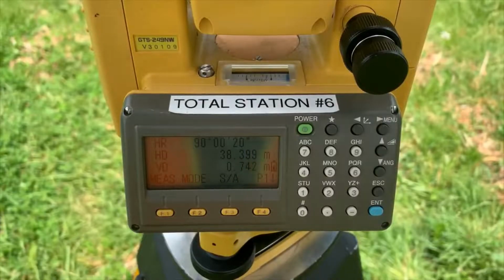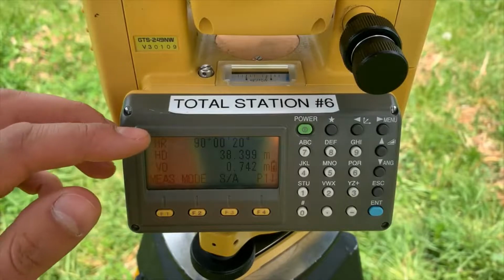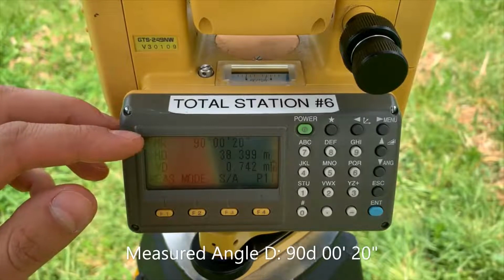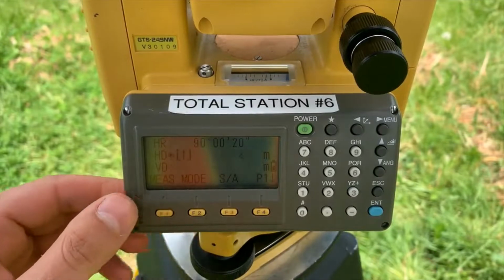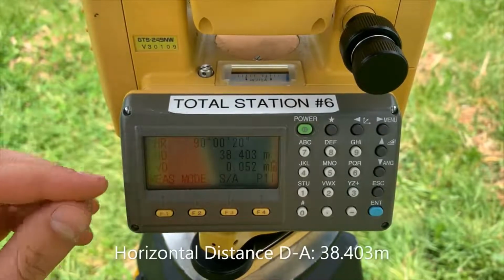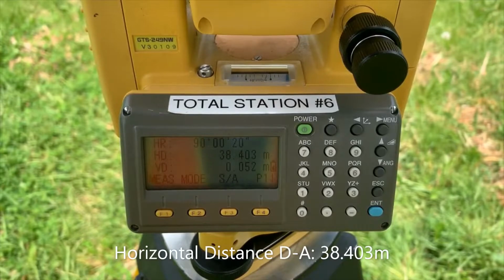So we've now sighted the total station on a prism set up over point A6, and we can see from that our horizontal rotation is 90 degrees, 0 minutes, 20 seconds. We can take a reading to see the distance, and our horizontal distance is 36.403 meters. And you can record that for the distance from D to A.